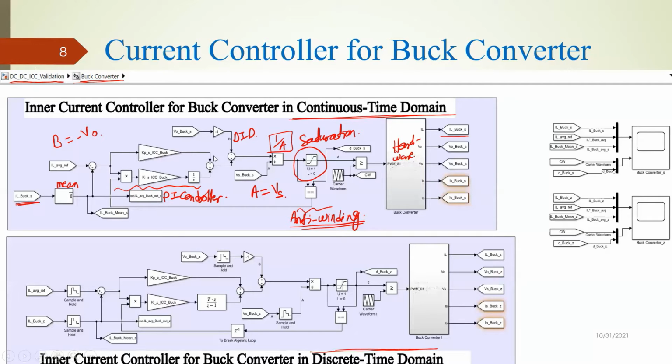So it's very important that you put some anti-windup for this integrator, and you can do this anti-windup for your enable and disable signals for the control. And also whenever you have the saturation block, you should have this anti-windup, so that your integrator does not accumulate some false values, or values outside the boundaries.